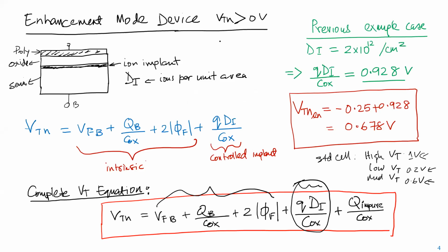No, sir. This is the part where even I'm not 100% sure about the process you explained right now. Oh, the melting part. I think that's one of the reasons they did it, and also the work function. The flat band voltage was also higher. But at that time the devices were almost 5 volts, like the 5 micron technology, so if you had a VT of 2 volts, it was fine.